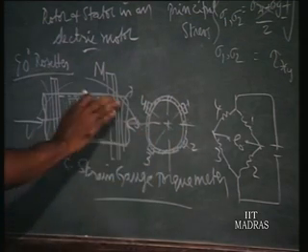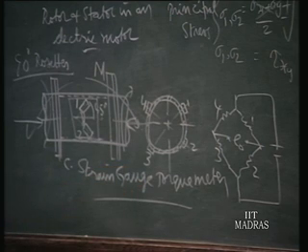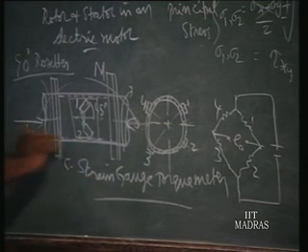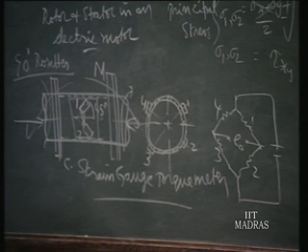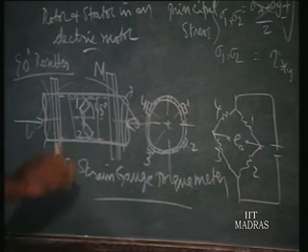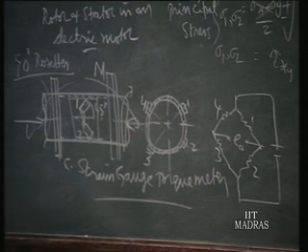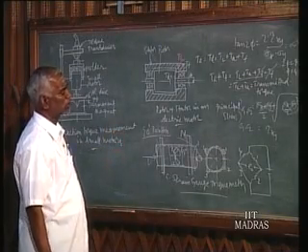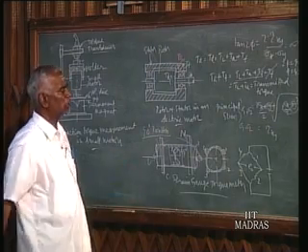The instrumentation responds only to the torque, and the bending moment as well as the compressive or tensile load on the shaft will not give rise to any error. Hence it is automatically foolproof for the other types of loading. So that is for rotating shafts. For rotating shaft torque, that is the transmission type, you can measure with any one of these 3 methods.